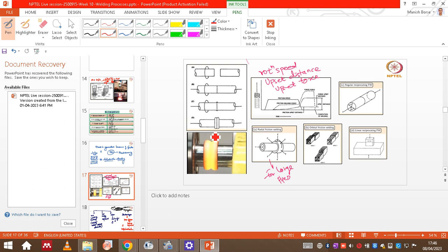Or else it can be of another shape, like a flat rectangular plate, or any cutting tool, which can also be joined through the friction welding process. And also some components, even if not in a rotating state, linear movement is sufficient to generate friction at the interfaces and to form coalescence by mechanical deformation, right?